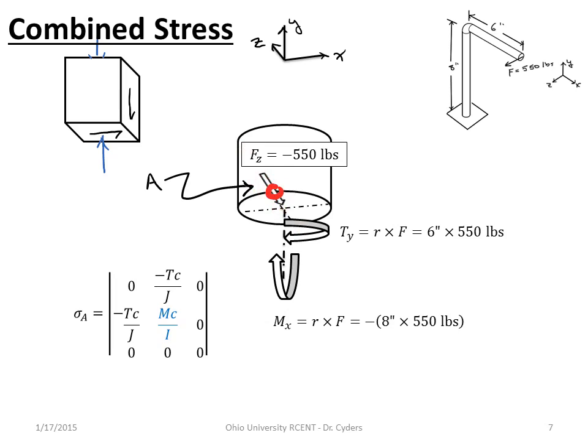So the two non-radial axes are going to be involved in our torsional shear. So we have tau xy is going to be negative Tc over J, and our stress in the y direction is going to be compressive, is going to be MC over I, where our moment, of course, is negative.